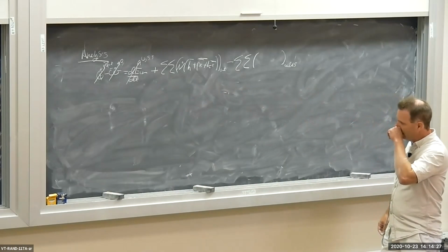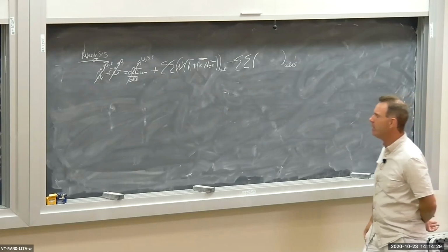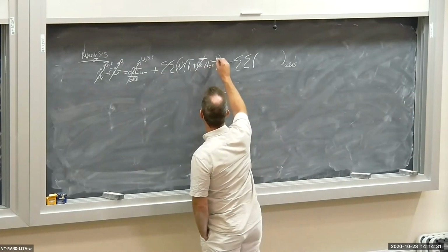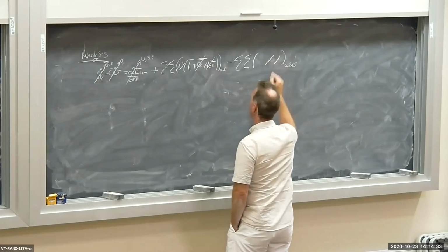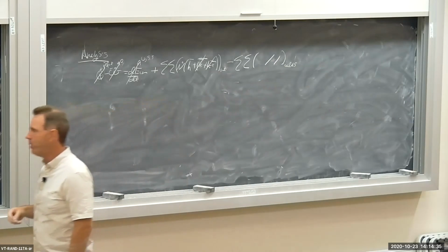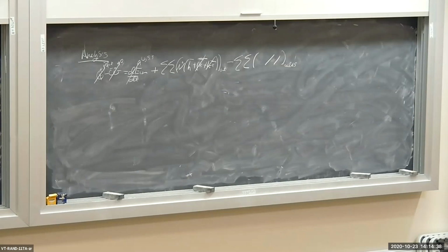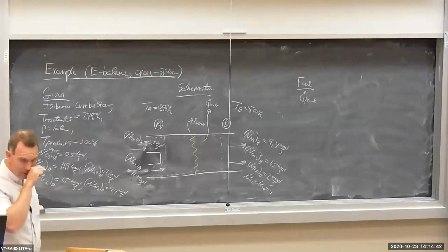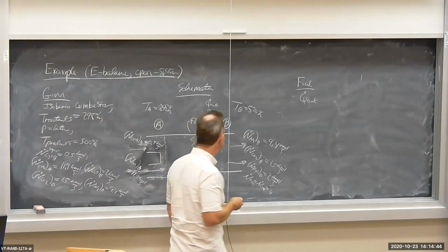I'm also going to neglect the change in kinetic and potential energy at the inlet and the outlet and for the various components. I have no information on the velocity of the flow or on a change in position, so I'm going to neglect the changes in kinetic and potential energy.